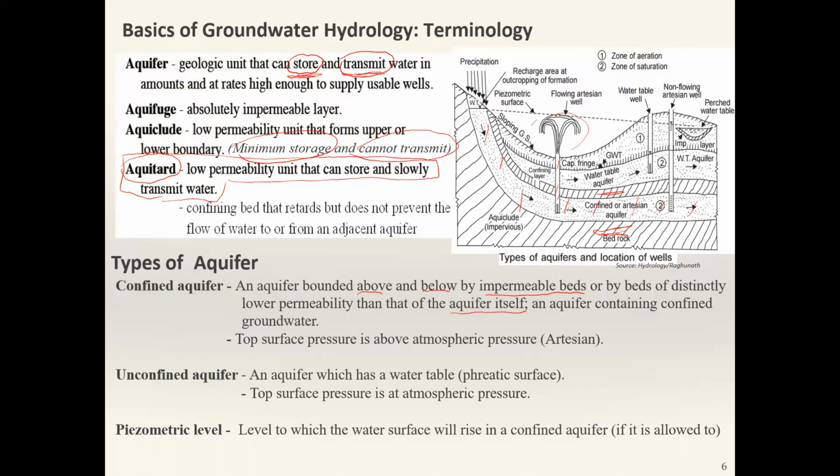In fact, if the hydraulic head of this well in this aquifer is larger than the hydraulic head gradient that you see somewhere here, then it will be acting as a spring, an artesian well. All the time the water will come out, right? So this is a pressurized aquifer.